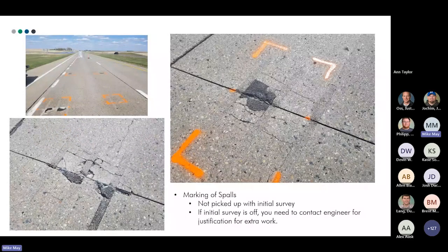All right, marking of the spalls. You can kind of see here the dowel bar retrofit. You see how some of that's breaking up in between. The dowel bar retrofit concrete was sound, but in between the dowel bars was completely shot. So we had to talk to the district and ask, what do you want to replace? What don't you want to replace? We needed to keep track of quantities as best we can.